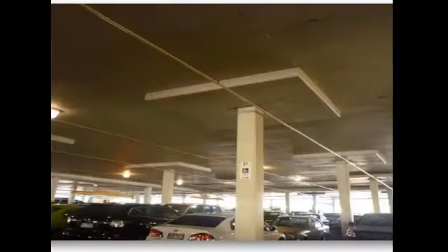So the advantages, the purpose, the disadvantages, and everything, it is so similar to that of waffle slab. It's just that I can see it is less stiff. The stiffness is lesser than that of waffle slab, and then it is lighter than waffle slab. So I think that's the clear difference between the two. So let's move to the 4th one, which is the flat slab. So this is a flat slab.